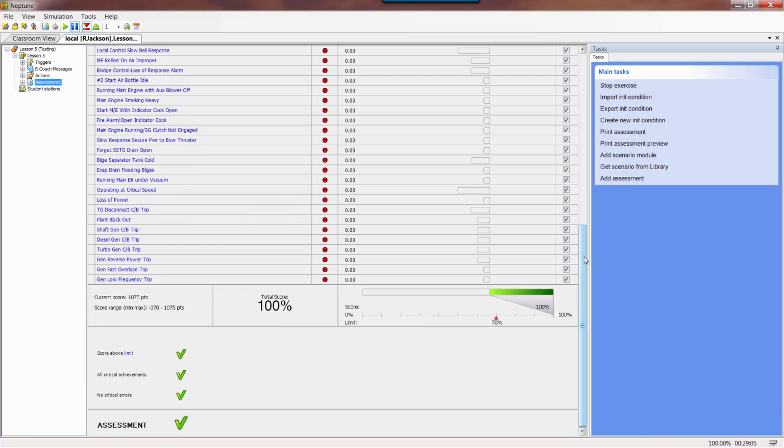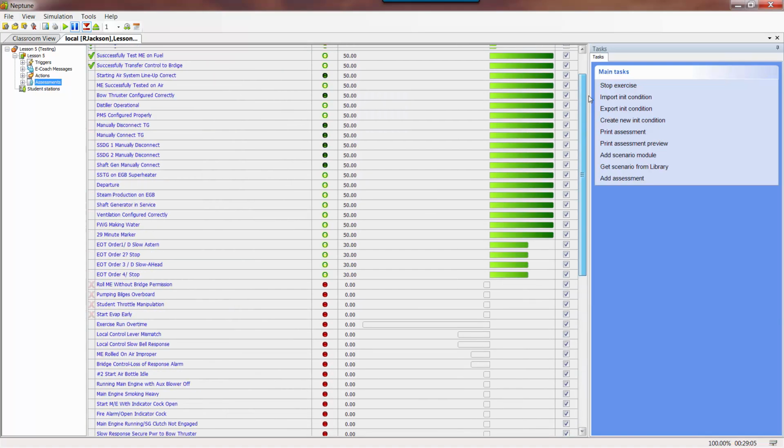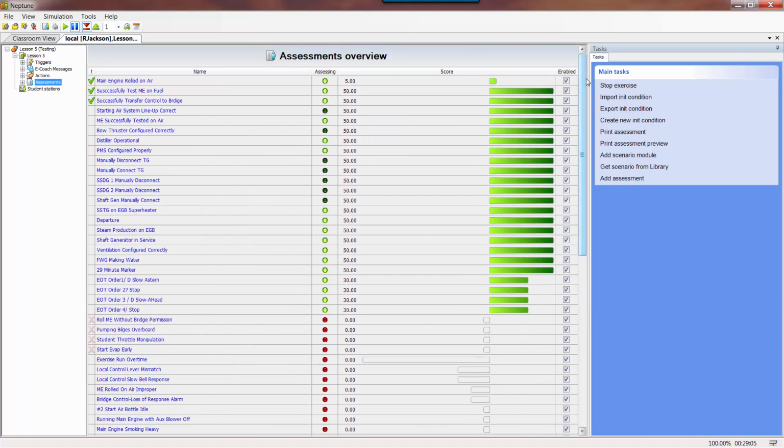As soon as I get departure or the engine restarts, I typically put the ventilation, cut off a couple fans, exhaust fans, and I keep an eye on my second screen. I leave one screen so I can keep an eye on the evaporator, and when the distillate condenser gets a quarter to half full.